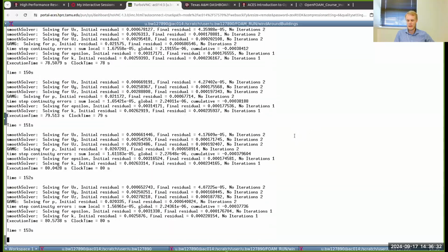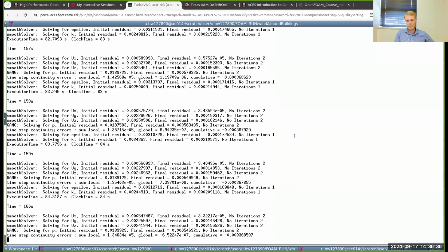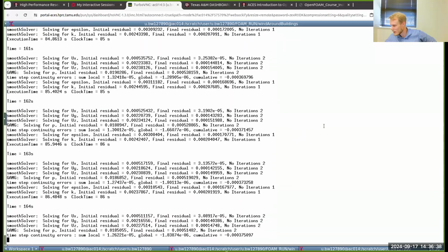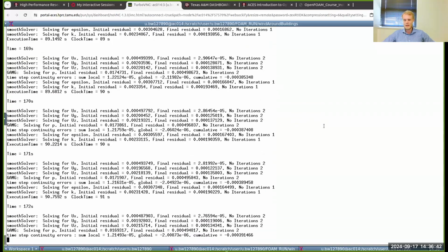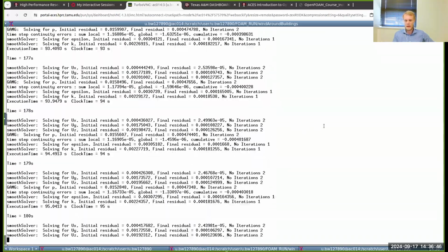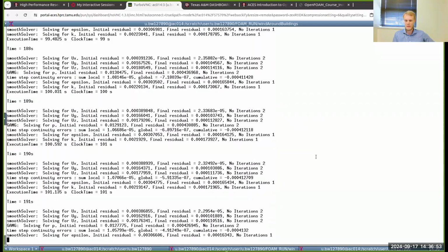I forgot what it was. Let me check what it was, disable SF_10. Then you should not be getting that fatal error. And blockMesh is blockMesh with a capital M. That's probably why it doesn't work, if it doesn't work.